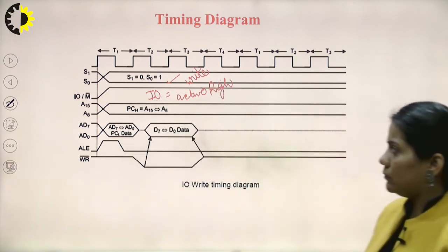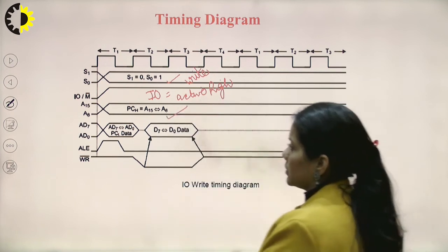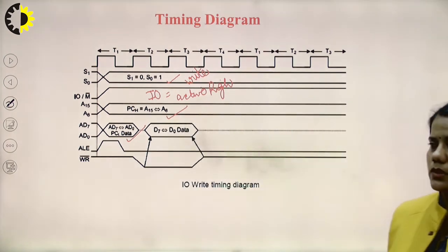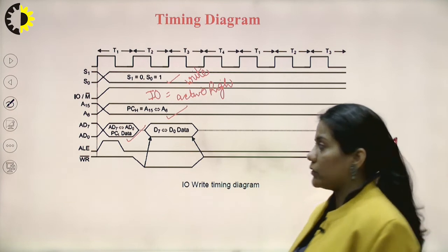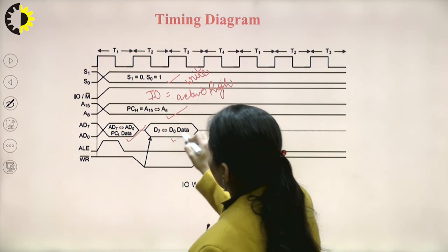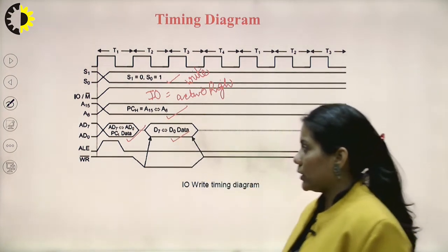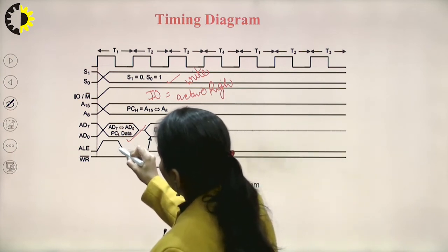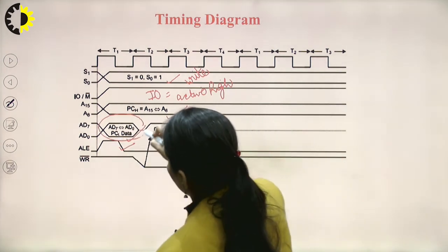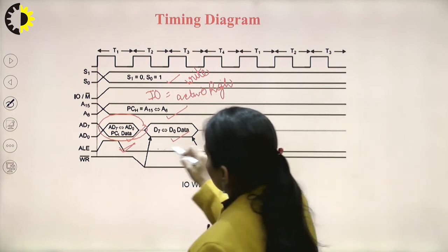Again, A8 to A15, the higher order address, is latched on the higher order address bus, and the multiplexed AD0 to AD7 bus is used to carry the lower order address during the T1 state. After the T1 state, this bus is used to carry the data. During T1, the ALE signal is activated and the lower order address is latched as long as this ALE signal is activated. After T1, this signal is deactivated.